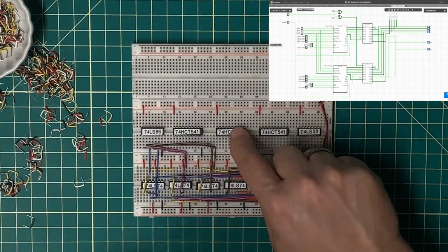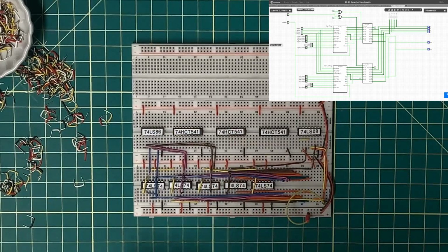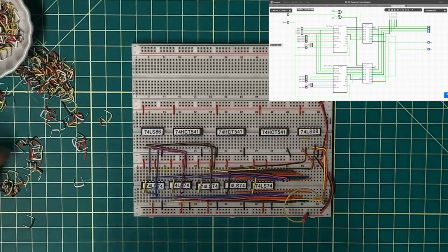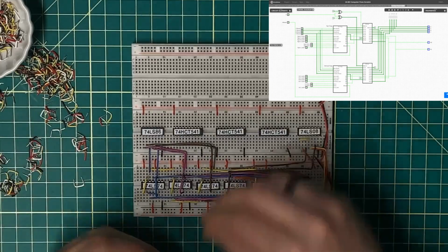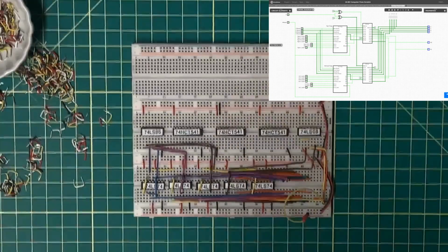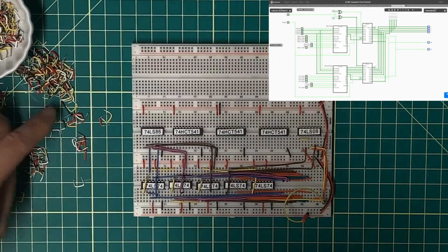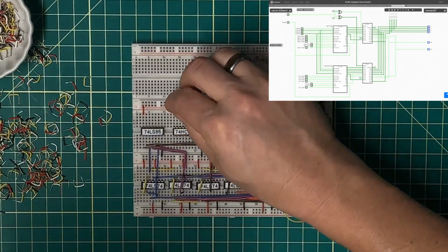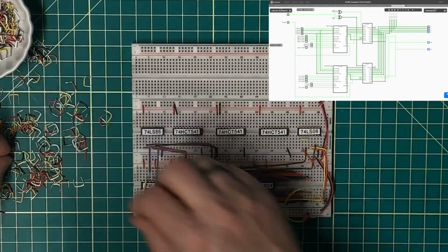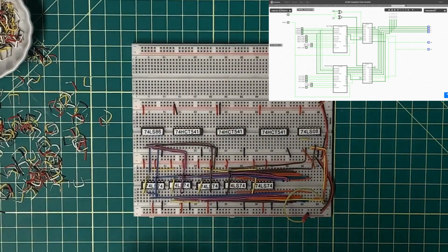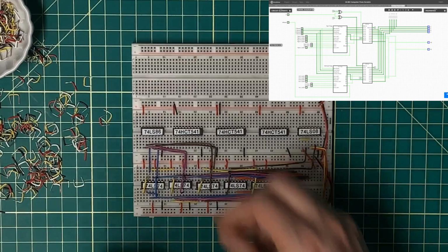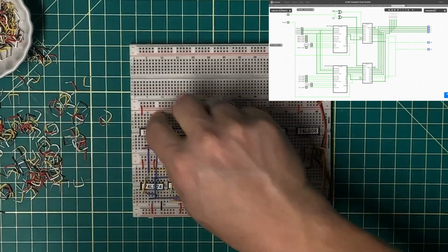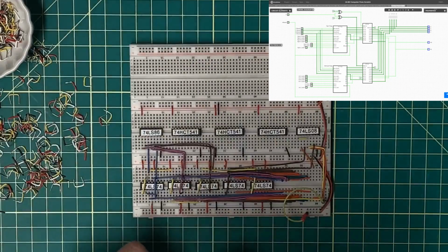Okay, this line driver is always going to be outputting, so I can take pin 1 low and I can take pin 19 low. That way it's always got output going. The other 2, I can take pin 19 low, and that will leave pin 1 available for, so I want to do 19 now. I think it's probably going to be easier because the exclusive ORs that are going to drive that are up here. So let me take pin 1 low.